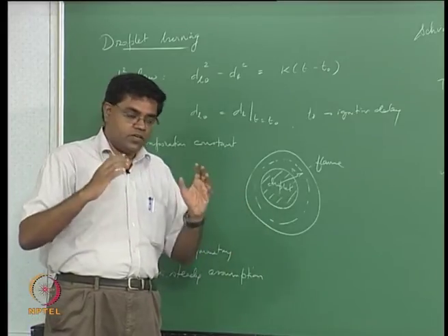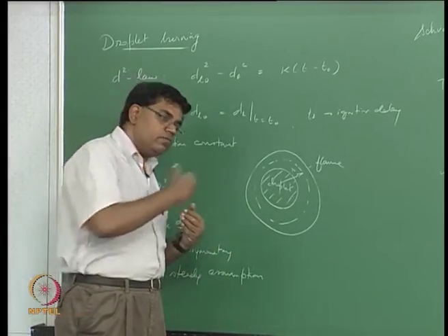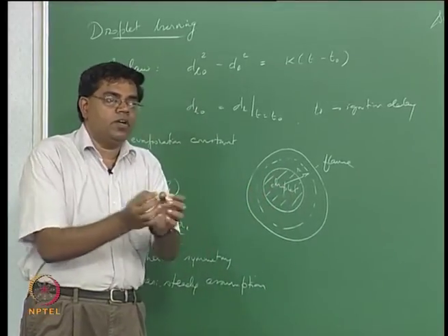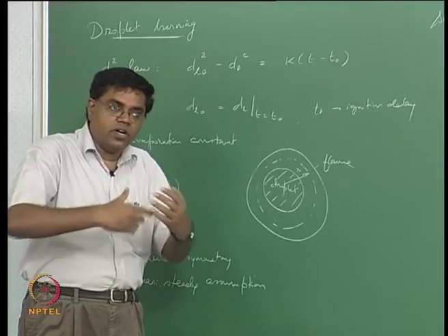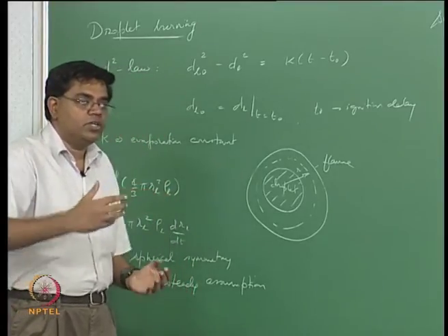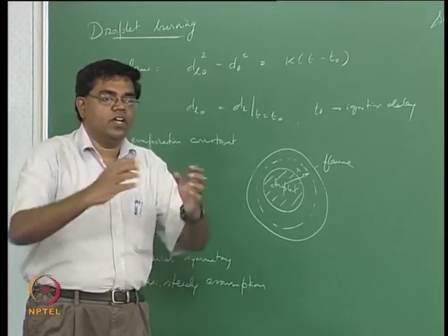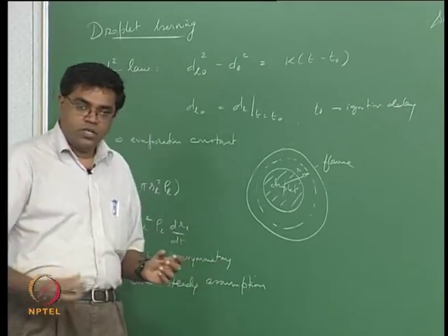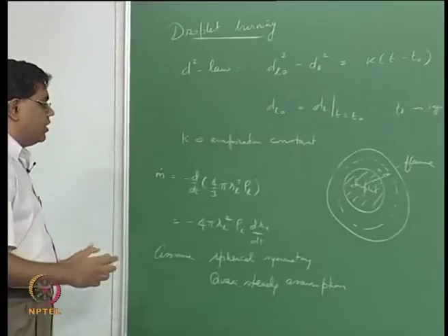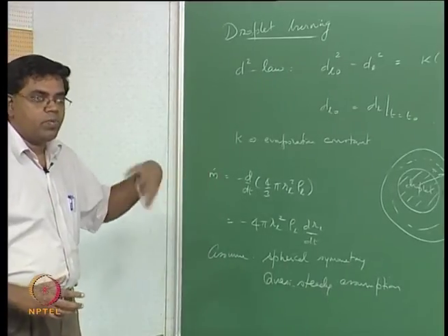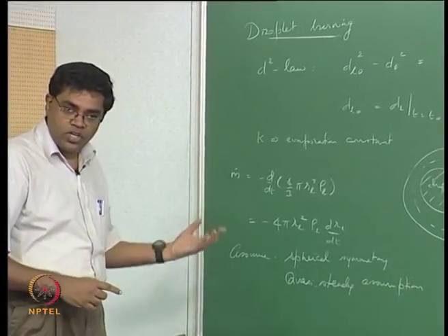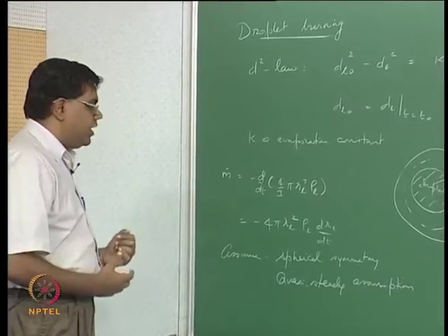grows. So towards the later part of combustion of the droplet, you have a smaller aluminum droplet and a larger lobe, and ultimately when all of the aluminum is burnt, the lobe closes and becomes an oxide droplet. So that is the final product. In both cases you get a liquid product, but in one case it is contaminated by some of the fuel that has got quenched without the flame being able to sustain.